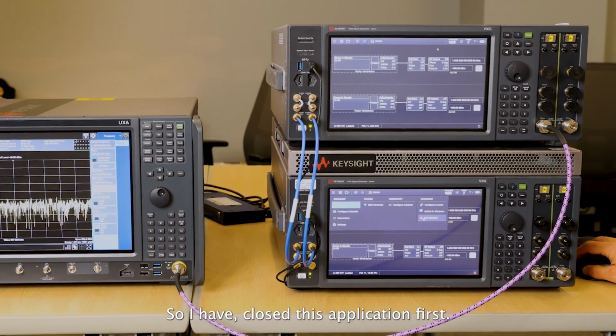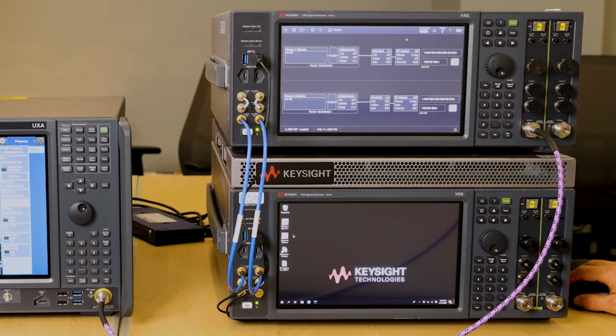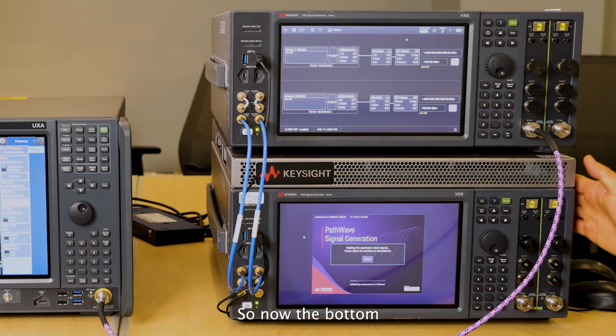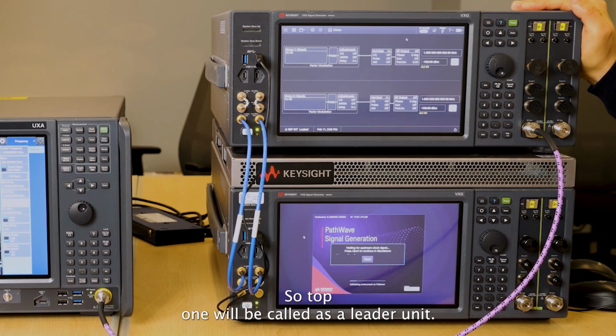So I'll close this application first. Then there are two icons. The top one is for normal use, but the bottom one is for the synchronization case. So I just double click this to start a new instance as a follower unit. Now the bottom unit is waiting for the control from the top one. The top one will be called the leader unit.